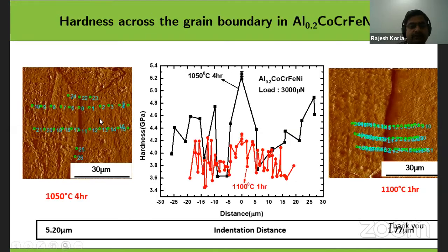And this is one way we have done in our group. This is basically a high entropy alloy, and we saw the grain boundary we are seeing right here, and we don't have any technique to see whether the chemistry of the grain boundary is changing or not. Then we thought about what can be an indirect way of determining, during heat treatment, whether solute atoms are precipitating here.